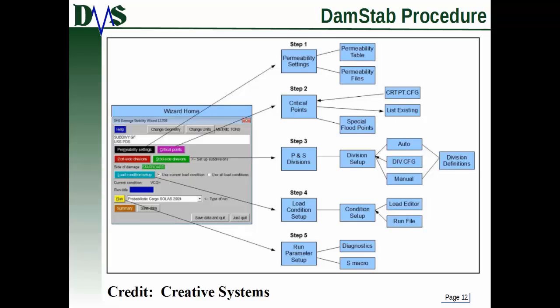Now, GHS is going to calculate that, but what you have to do is tell GHS how the geometry of tanks lines up into different subdivisions so that GHS knows what probability to assign to each flooding condition.